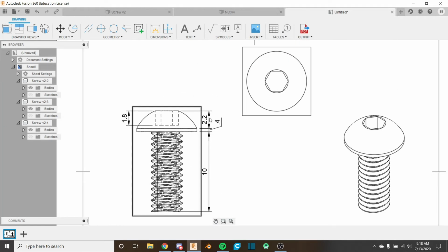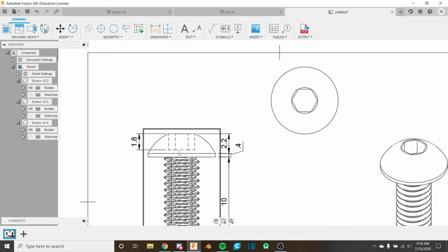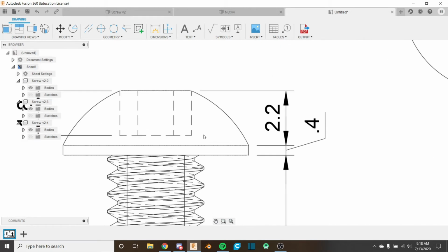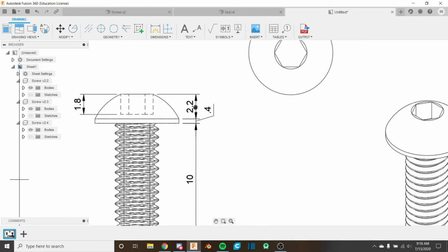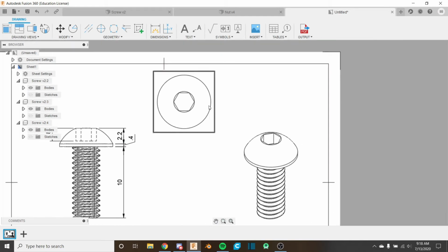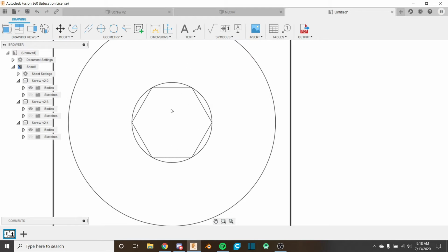So now we have all the height information, and that's what I want to get out of this. It's good practice not to overclog one drawing with too many dimensions, as that can make it hard to read and get all the dimensions. I could add the diameter of this here, but I'm not going to. I'm going to put the diameter and the information for the driver here.